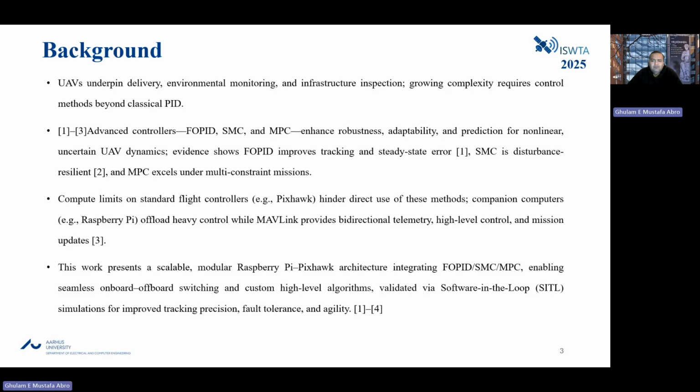We cannot program these high level control algorithms, for example, fractional order PID, sliding mode control, or model predictive control. So this is one of the major issues that people working on these high level control algorithms are unable to deploy them on Pixhawk.